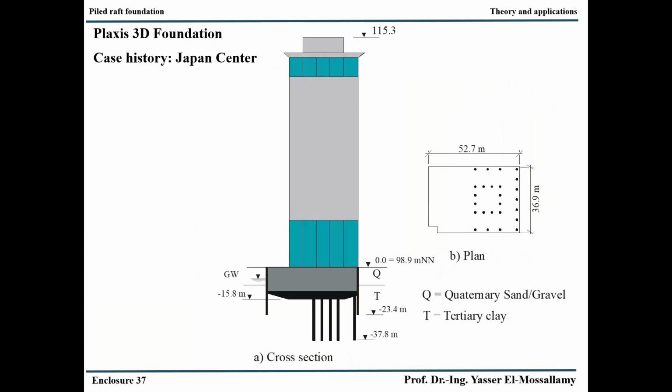Now we go to the next era, where we developed the numerical modeling of the piled raft foundation, and I can show you an example of the software Plaxis, where I contributed to the development of the beam element model to model piles in 3D analysis. What is the problem of modeling piles in 3D finite element analysis? It is the number of elements. If you model the piles as volume elements, you need thousands of elements, and very quickly you come to millions of elements for the whole structure. This, of course, is a problem for computer capacity and runtime.